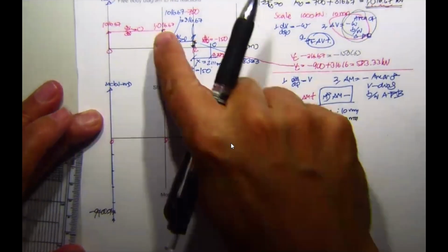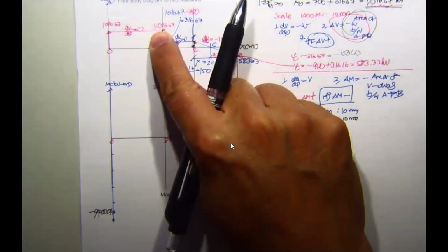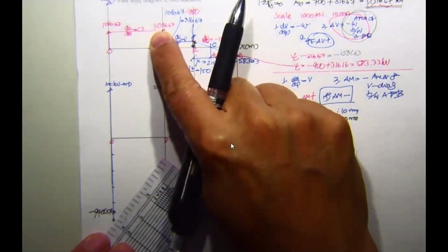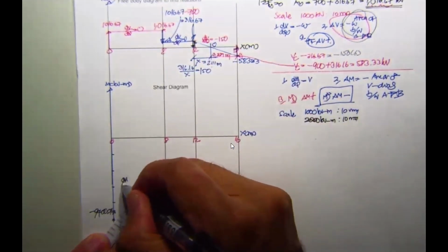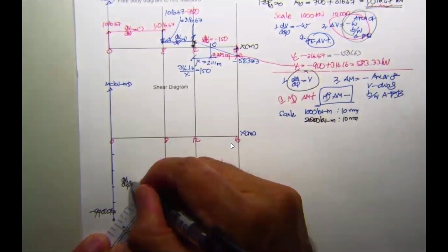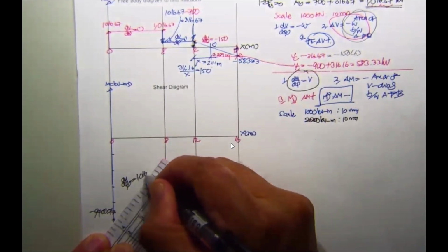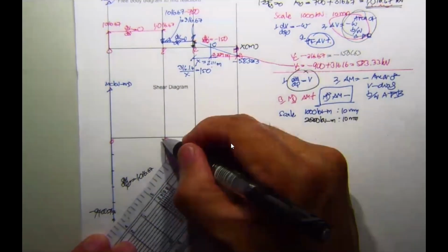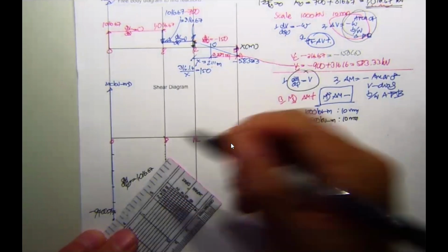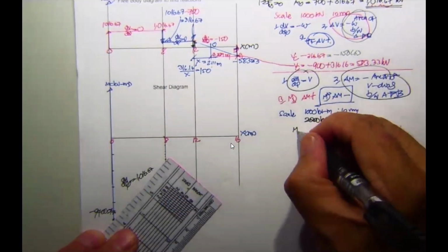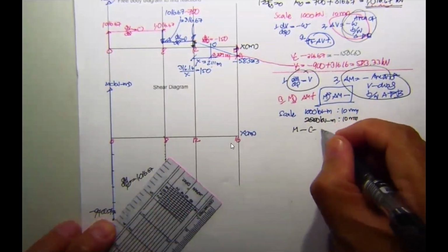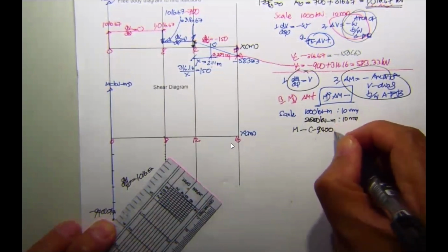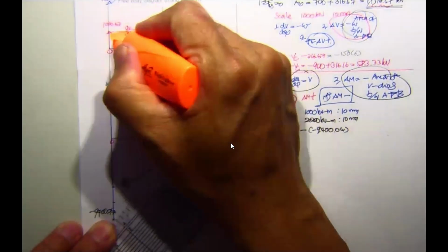Then the shear is always positive, so we should have dM/dx over here equal to 1016.67. Then when we arrive here, what's going to be the moment here? Coming into this one, M over here minus M over here, minus of the minus 9,400.04.